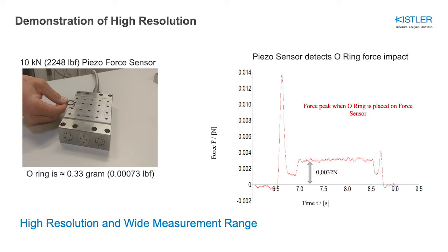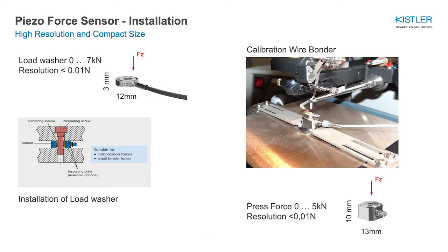Next, we will look at compact size and further discuss rigidity. High resolution and wide measurement range combined with compact sensor size are very desirable features of piezoelectric sensors. Furthermore, the high sensor rigidity, which means low overall deflection of the sensing crystal during measurement, allows for excellent dynamic force measurement performance.